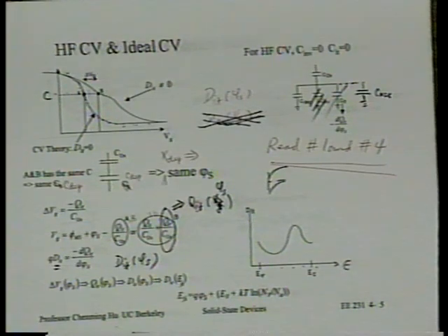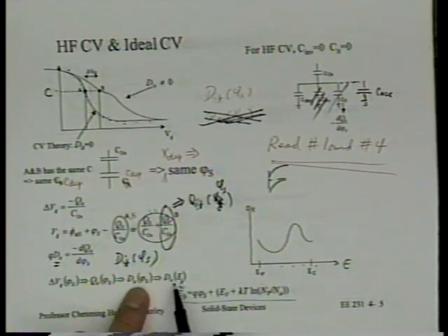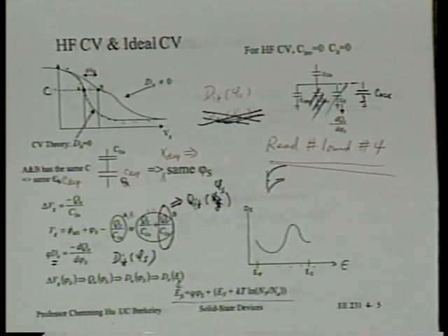I don't know how to use mathematics to clarify that, but I'm trying to clarify it with the subscript Fermi level, and if you wish, you can read this. But I think it's better to explain in my own words the relationship between these last two quantities. When we scan phi S, we're really scanning the trap we're probing in the E space. And the relationship is this: as we change phi S, we're changing E, we're scanning, we're probing.